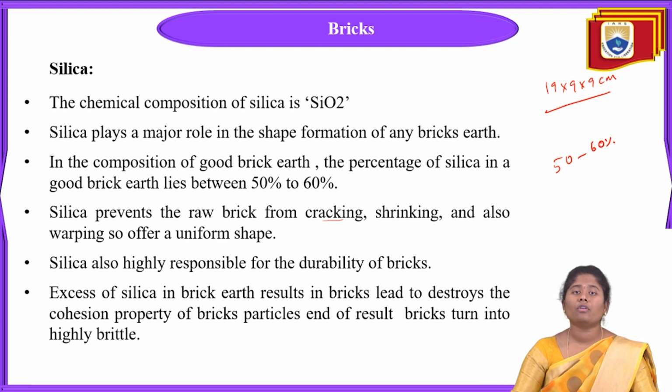And excess of this silica will destroy the cohesion property. Cohesion property is nothing but attractiveness between the particles. This cohesion property will be destroyed if you use excess silica, and the bricks can end up with a highly brittle nature if you use an excess amount of silica.